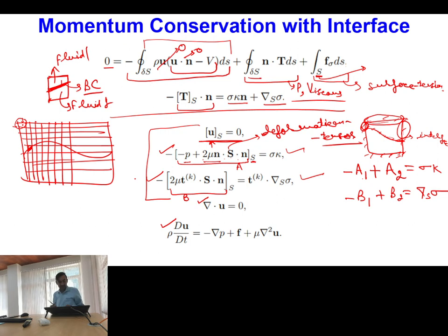Whereas the nature of individual continuity and momentum equations is the same as that for single phase flow. So it means for the two fluid approach, your continuity and momentum equations remain the same as the ones we use for single phase flow, but the interaction between the two phases is coupled through the interface boundary, and at the interface boundary these will be the communicating boundary conditions which will be active. All are clear with this point?